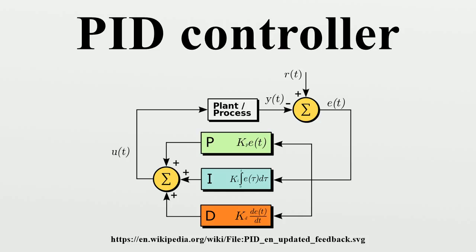Ziegler-Nichols method. Another heuristic tuning method is formally known as the Ziegler-Nichols method, introduced by John G. Ziegler and Nathaniel B. Nichols in the 1940s. As in the method above, the I and D gains are first set to 0. The proportional gain is increased until it reaches the ultimate gain, Ku, at which the output of the loop starts to oscillate.